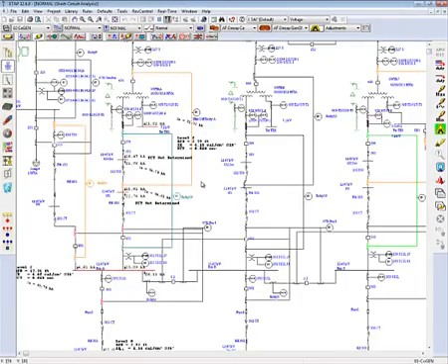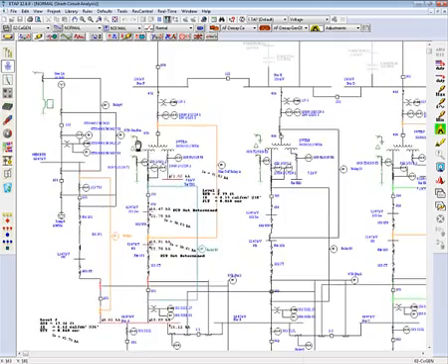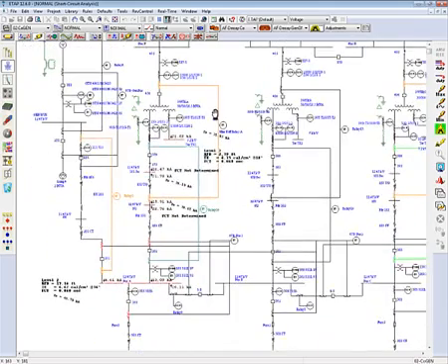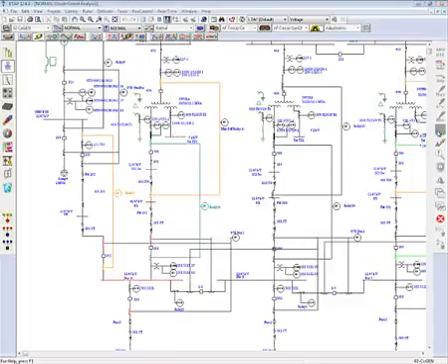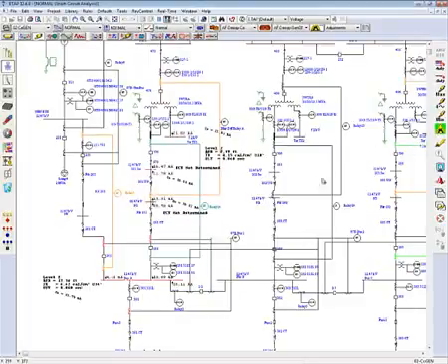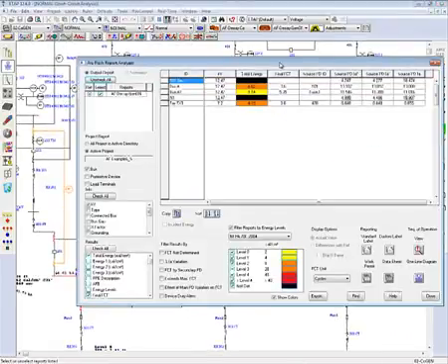Now in this system I have cogeneration and various differentials set up. So let's go ahead and execute this scenario and open up the arc flash result analyzer. As you can see here on my report analyzer, I have 2 locations which are color-coded black. I have set this up to identify which locations have fault clearing time not determined.